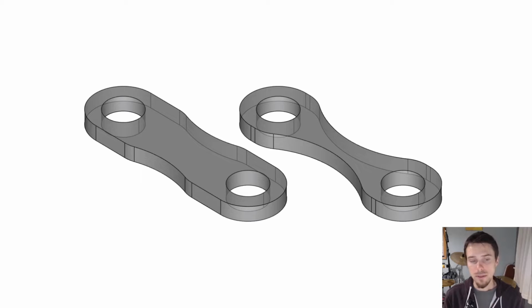To do so, we're going to model the part in FreeCAD. We're going to set FreeCAD up so that it can very easily change that dimension for us. We're going to set up a simple analysis in FreeCAD, and then we're going to write a little bit of Python to do it automatically, but completely outside of FreeCAD. So you don't even have to have a monitor. You can run this on a server, and you can see the results of all your analyses afterwards.